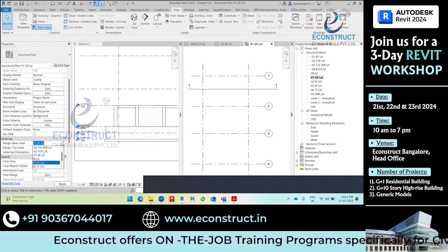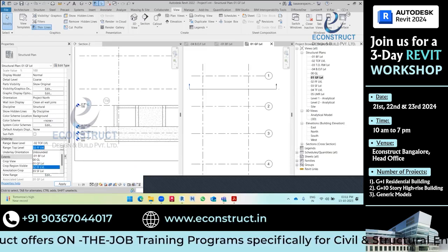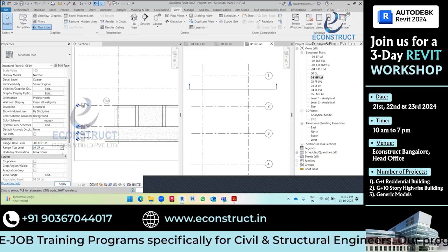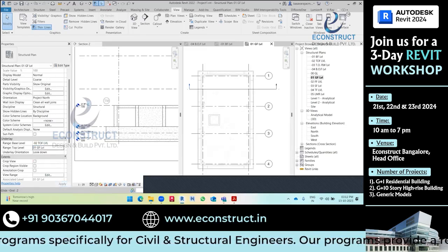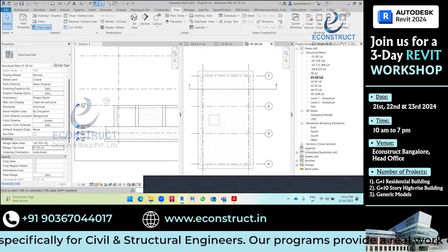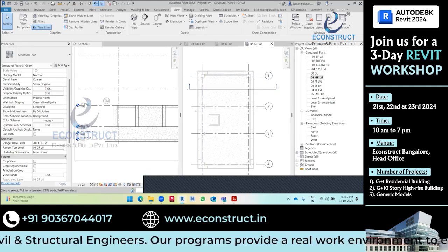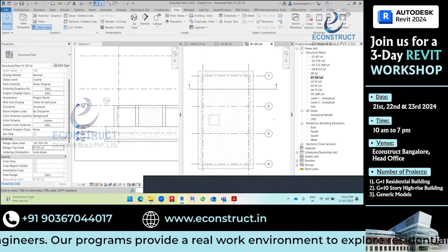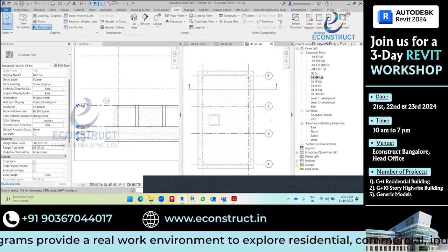For example, top of the footing level, base level. Top level, you just take ground floor level, and look down again, because we are looking from the top, no. Apply. So you can see up to top of the footing level in the ground floor level, so that you can model it with the help of these references. Okay, like that you can select the underlay options.